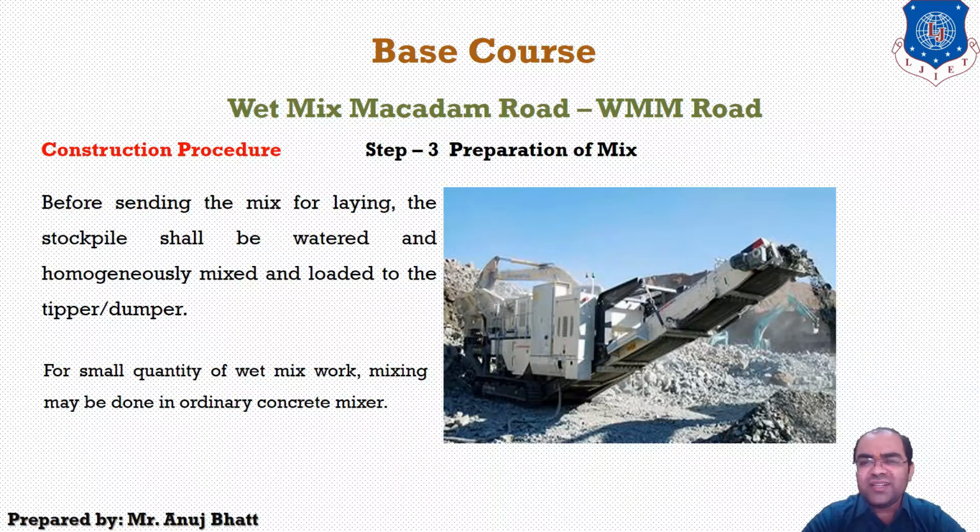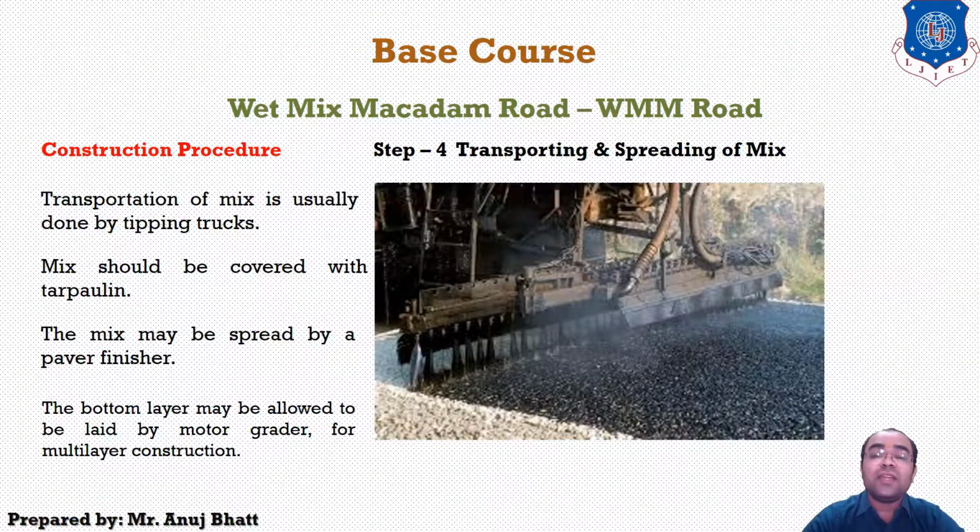Now, the optimum moisture content for mixing shall be checked and confirmed. While adding water to the mixture, due allowance should be made for evaporation losses also. However, at the time of compaction, water in the wet mix should not vary by more than 2%. If during compaction the water varies by more than 2%, that will create loose material in the mixture.